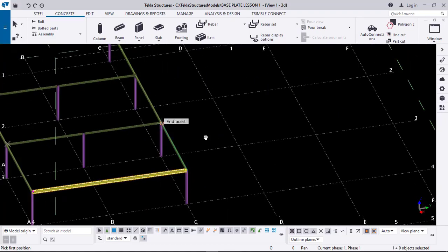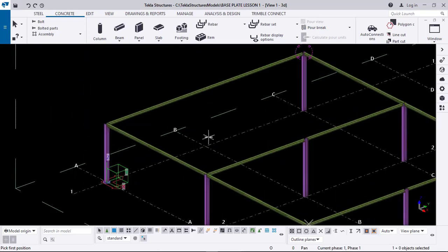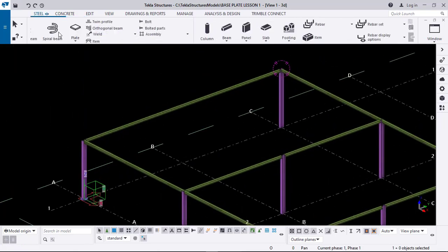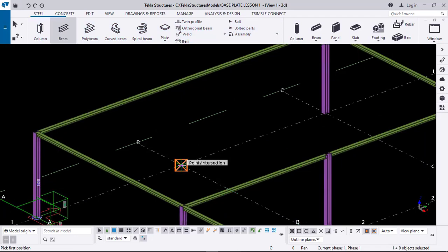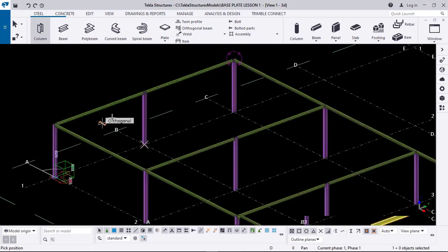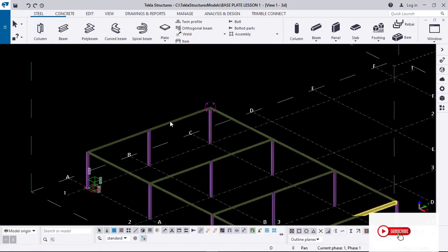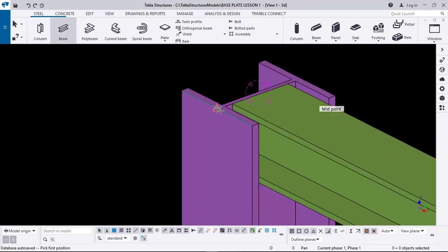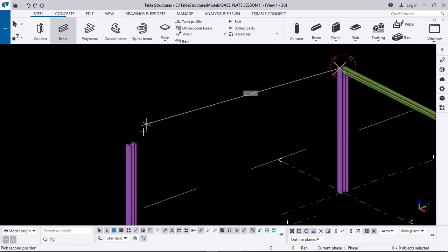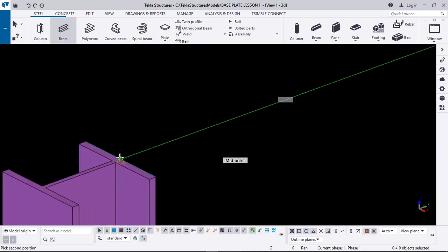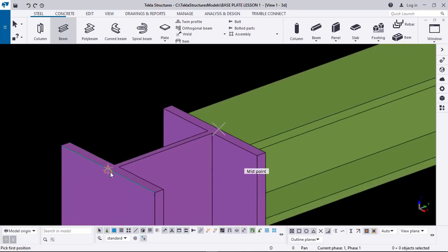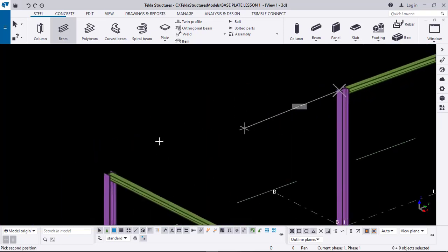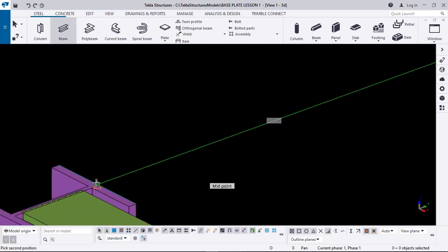Okay, so again, this is okay. Then again, we will also insert a steel column here and remove this beam and insert it back, because we want to use a span of 5.5 meters. So just click on column and insert the column here. Where I want my pin to connect, and then click on the next face again, and click on this face again, and go to the next one again, and then also click on this face again.